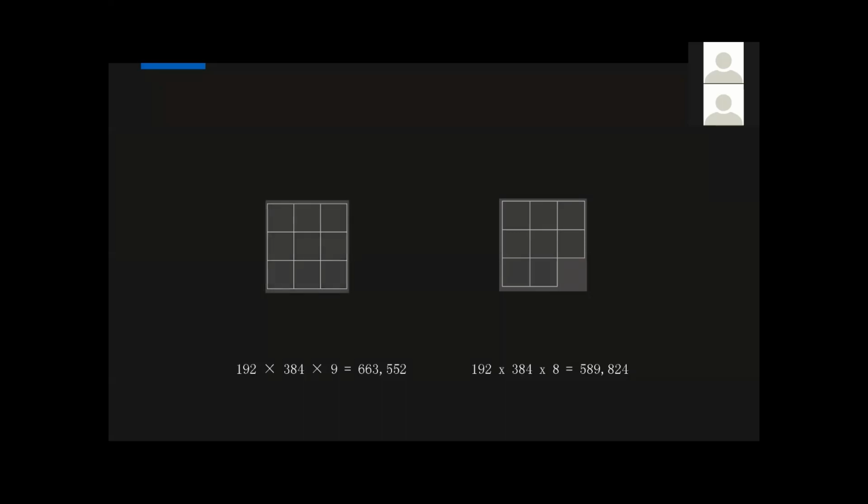So it doesn't matter whether you connect 7 panels, 8 panels, or even 9 panels. The loading capacity for those three conditions is the same, always the same as 9 panels. That's the most important thing of this training: we're always calculating the loading capacity for every port based on the minimum rectangle that covers all the panels on this port.